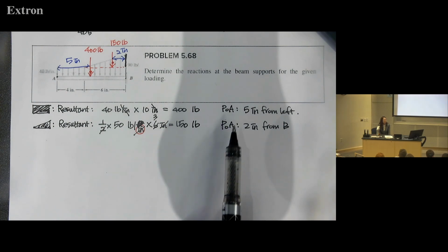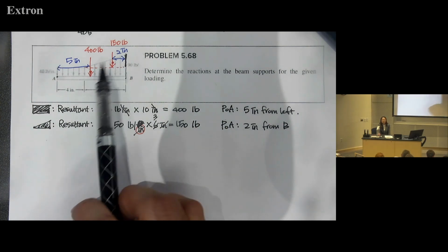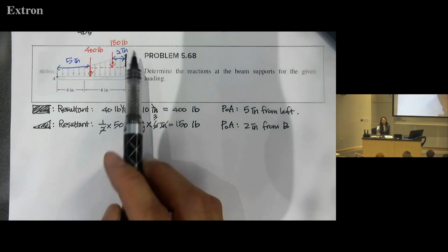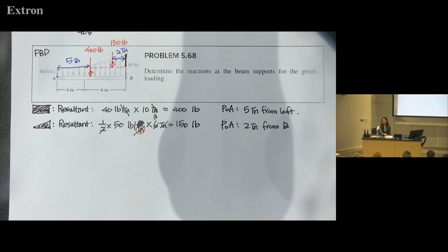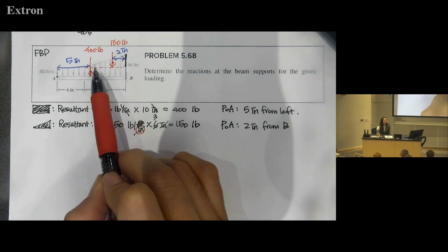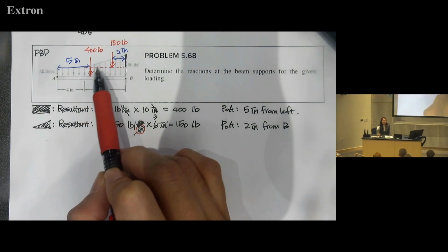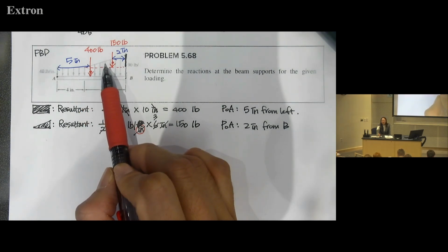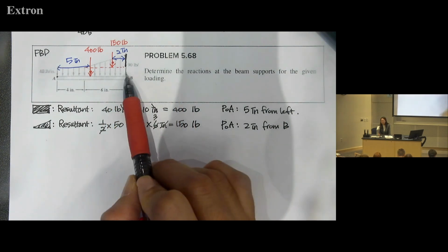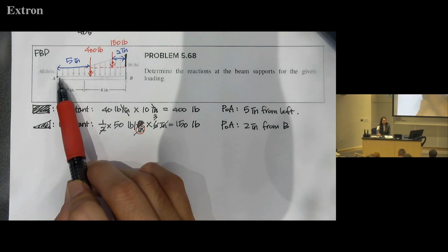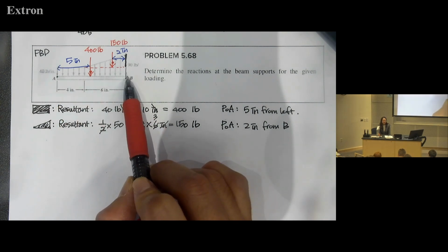Okay, so after this analysis, plotting this one is greatly helping. It's part of the free body diagram here. So FBD. And now we simplified our distributed load, and to complete the free body diagram, we can add the reactions at the support. So A is free, no reactions. And then B is fixed.